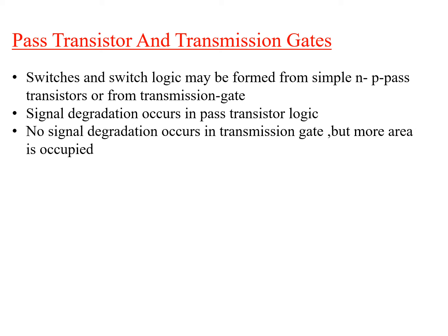So here when you apply 5 volts at the input, you are not going to get 5 volts at the output. Some part of your voltage, let us assume 0.7 volts of whatever you applied, will be used by the MOSFET to go into the conduction mode, because 0.7 volts is the required voltage for the MOSFET to activate itself.